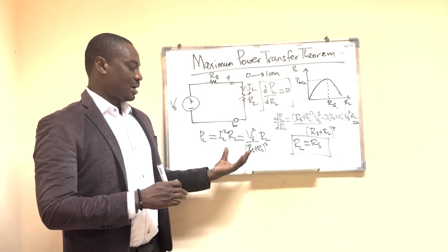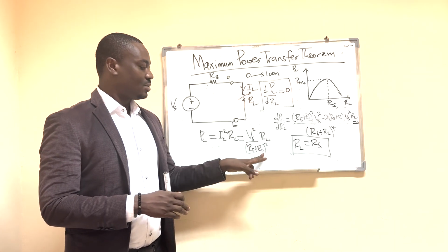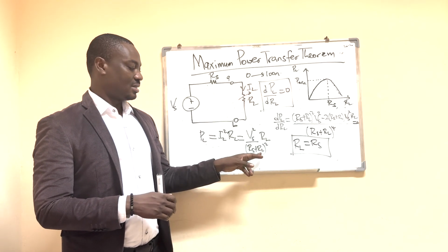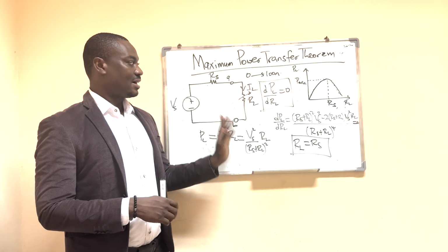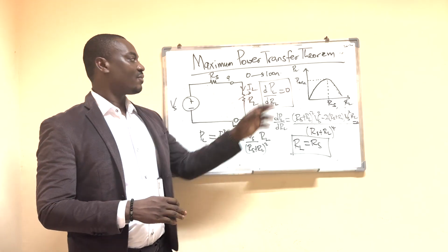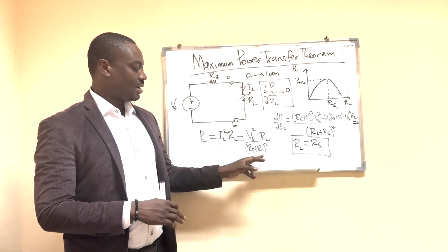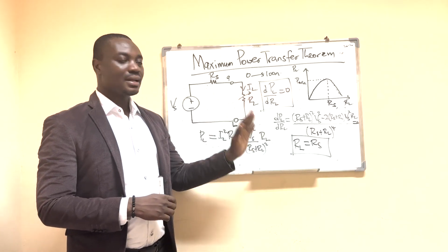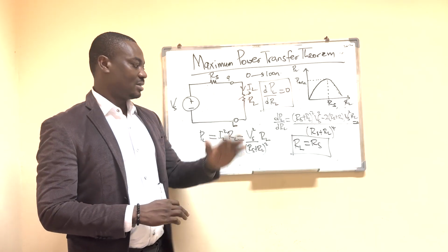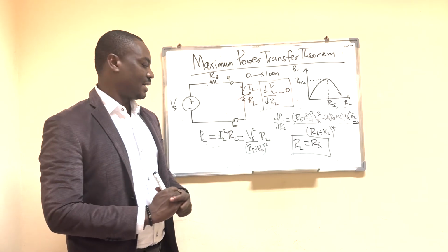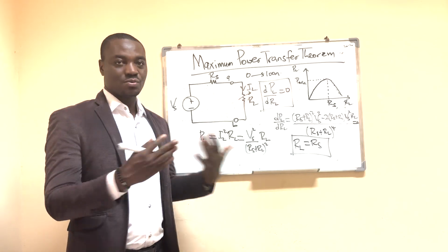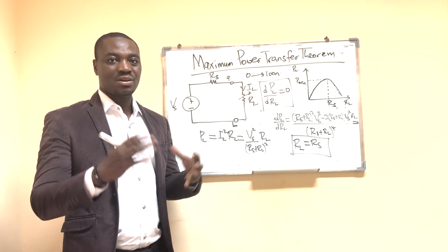So in order to get the maximum power, I can start from 0, put that value in as my load resistance. Then after that, I'll pick another value within the range of operation of the variable load resistor and calculate the power again, right? So I can start from 0, 1, up to the 100th value within the range of operation of the variable load resistance. Once I'm done, I'll look through all the various powers that I've calculated and pick the maximum power, I mean the highest amount of power dissipated.